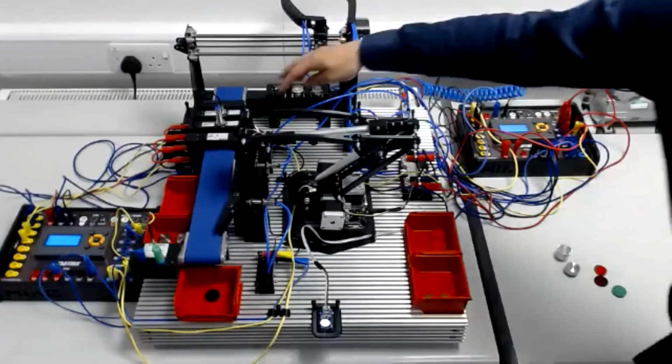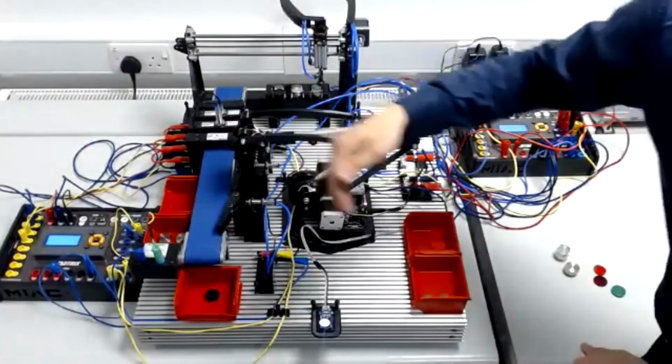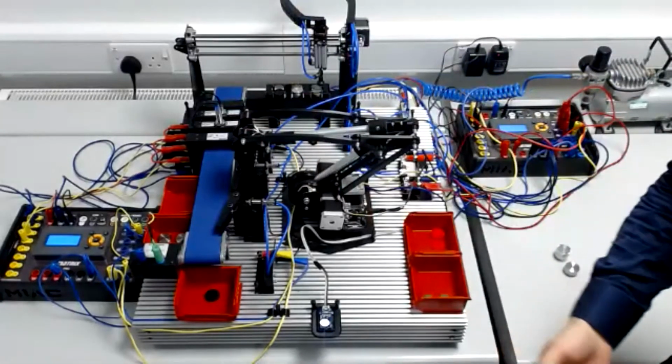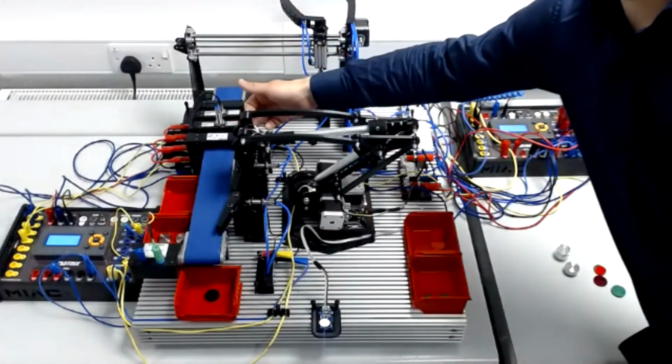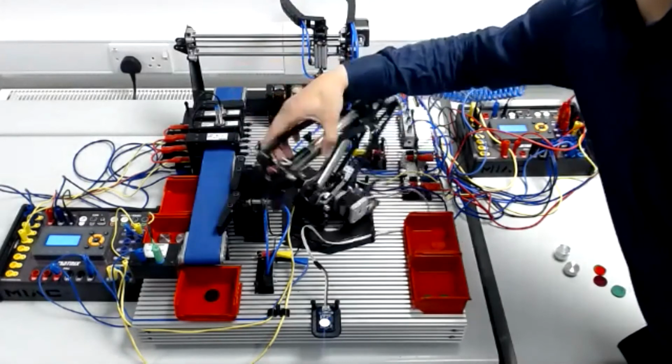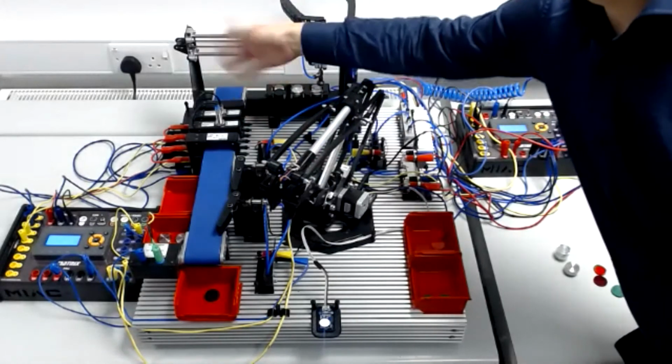Just to give you a bit more explanation about what sensors are doing in our operation, the exercise takes them through from starting with one sensor, building it up to the 4 sensors. We've got light gate, inductive, capacitive, light gate in that sort of order. If I spin it, you can see it. It goes open, so it starts the sensing motion.